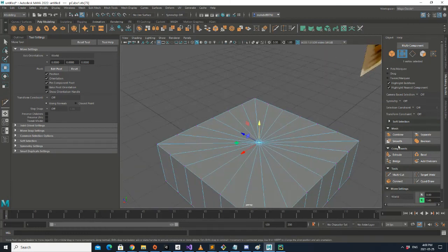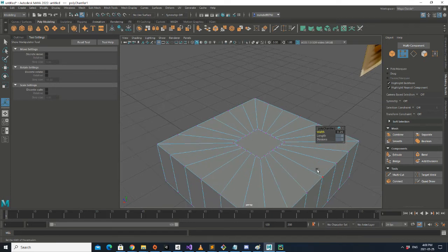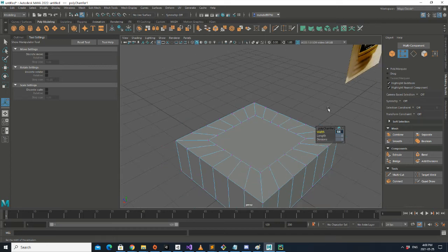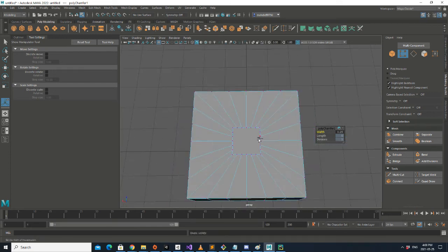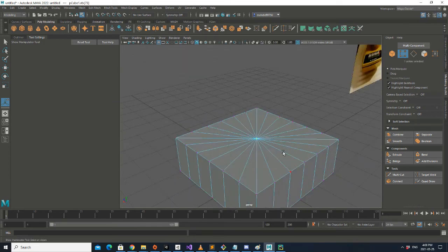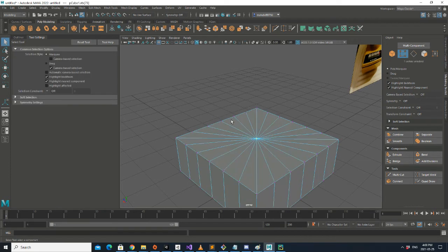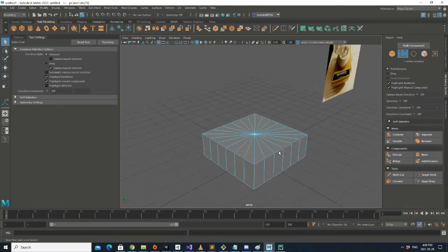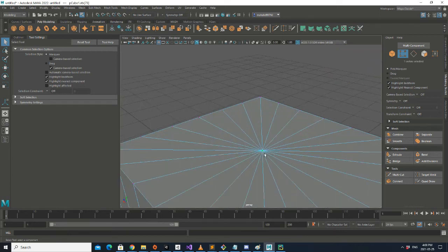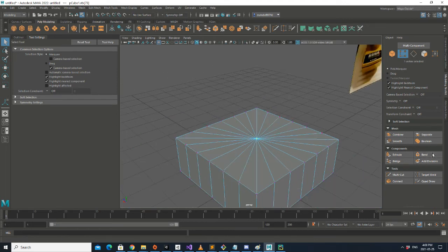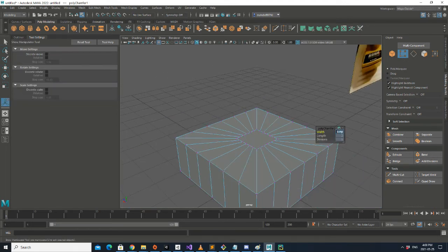Yeah, and now we are going to use bevel here, and that's really interesting. You will see that bevel also works here, and let me just put 0.6 for the width of my bevel. Sorry. So again, go ahead. How did you select the center? Just right click on your model and then go to vertex. Oh, okay. Thanks. Yeah, and then you can select vertices. Just select the center vertex. As I said, select the bevel. Put whatever number you want. I would go with 0.6.